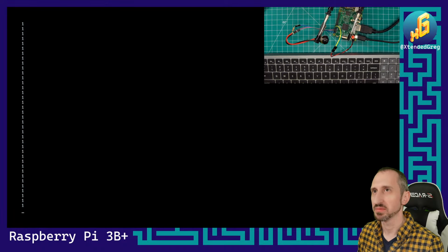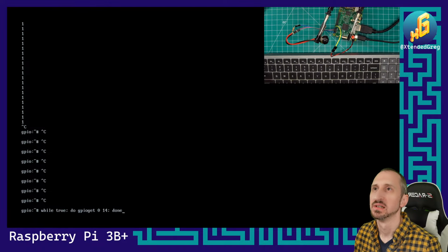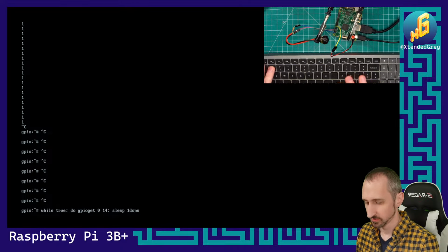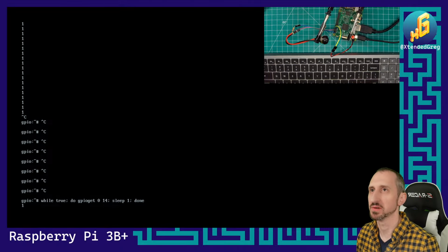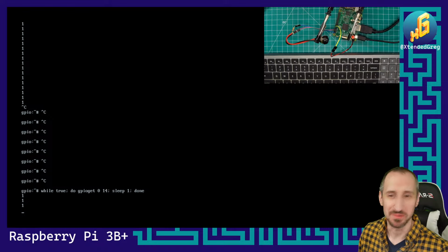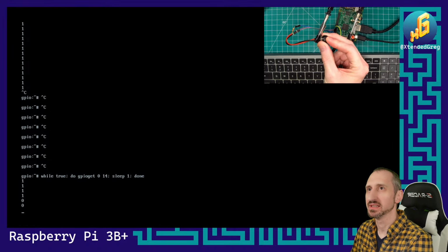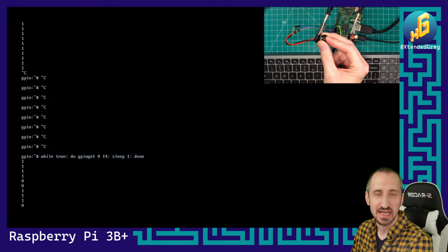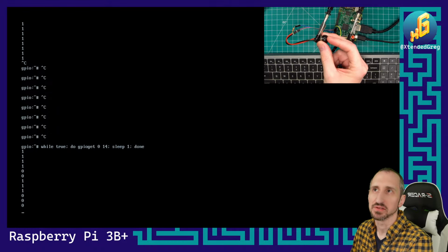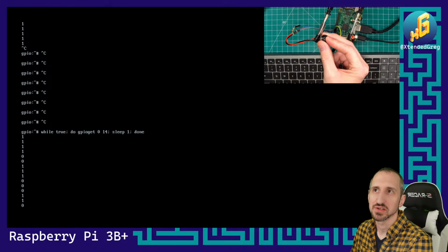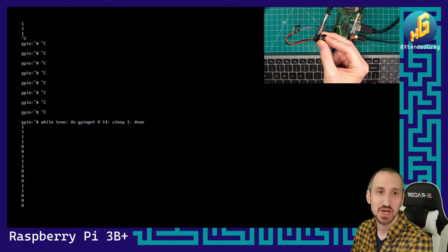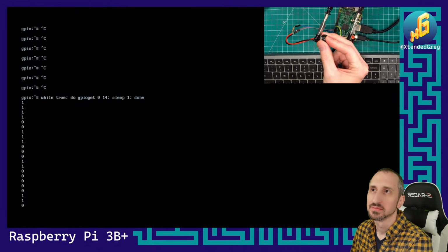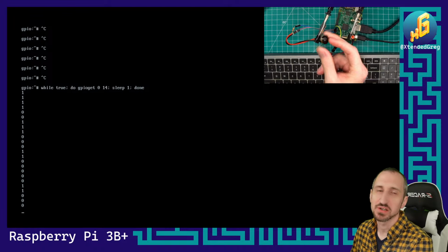So right now it's going, we didn't put a sleep command. That's probably not great. Let's put in a sleep command here. So we'll do sleep 1 semicolon as well. There we go, that's more reasonable. So now as I press the button, we see it updates in real time, but because we have that delay, we're not actually reading the bounce. We're only reading it at a certain sample in time, and we're just checking whatever the present state is. So that makes it a lot easier to track.